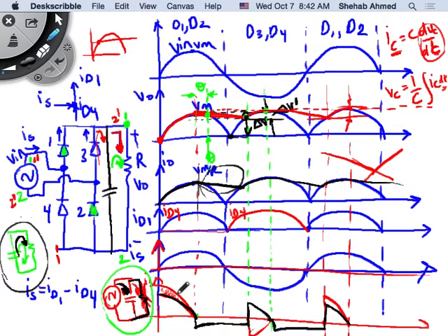So the capacitor current, okay, when the red waveform is coming from the supply, when I'm connecting my source to my RC circuit here, my source is feeding my capacitor, charging it, and that's the bulk of what's happening. It is also feeding current to my resistive load. So a small amount of this red waveform is going to go to my resistive load, right? So that's why I decreased this by a small amount. And then the rest is used for charging the capacitor.